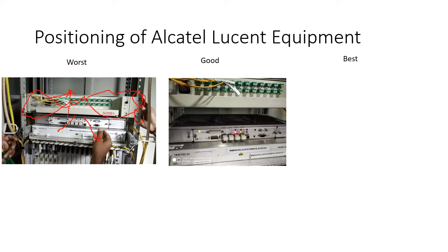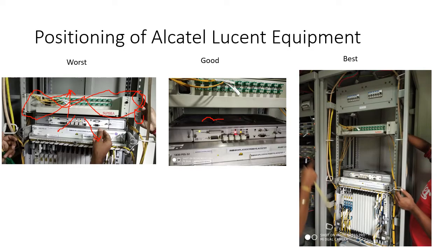We see the fins of the exhaust fan mounted at this place. Now this air has more volume and it is getting proper area to cool down, and it can now go on the upper side also, because the space has been increased. If you look at this last photograph, this is the best installation, because now further